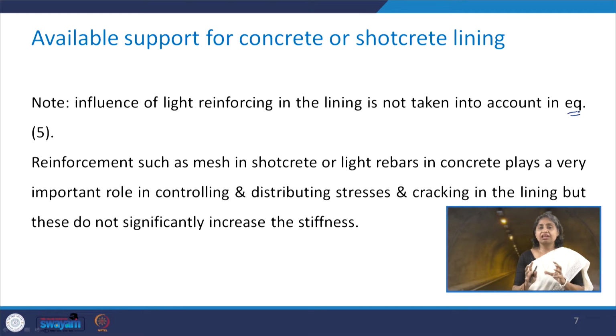However, they really do not increase the stiffness of the shotcrete or the concrete layer significantly. Therefore, it is reasonable to assume that there is no influence of this light reinforcement in the lining as far as the stiffness of the shotcrete or the concrete lining is concerned.